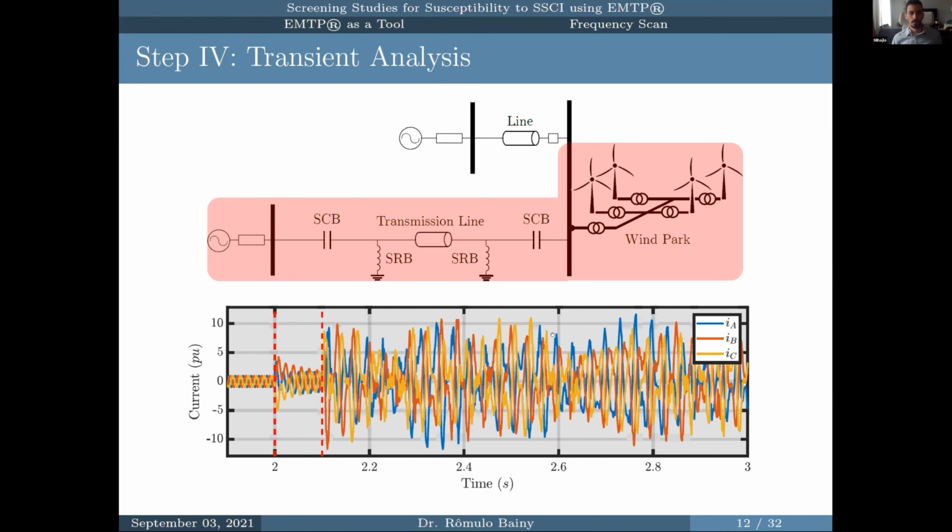Sounds good. So they were probably from the protective relays that were doing the measurements. You would have the cosine and sine filters with a gain of less than 1 at 30 hertz, and the anti-aliasing filter probably had a gain of more than 1. So you don't really know what the actual gain was and how accurate some of those magnitudes were.